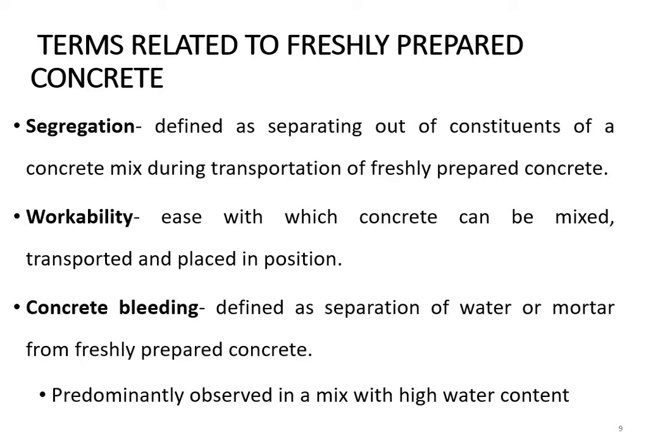Some of the terms related to the fresh preparation of the concrete. When you are freshly preparing the concrete, these are some of the properties that you need to take into consideration. First one is segregation, defined as the separating out of the constituents, such as the aggregates, from the concrete mix during transportation.